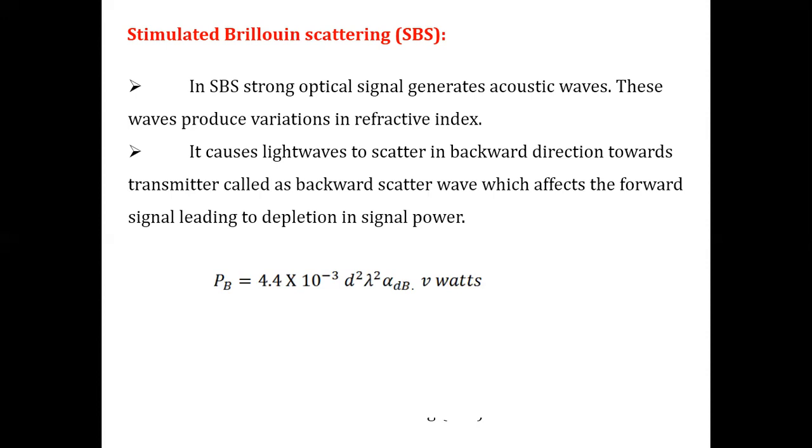Once again, stimulated Brillouin scattering occurs when we modulate light through thermal molecular vibration within the fiber. If the light gets scattered, the scattered light appears as upper and lower sidebands, which are separated from the incident light by the modulation frequency. The frequency shift is a maximum in the backward direction and very small in the forward direction. So mainly this SBS will flow in the backward direction.